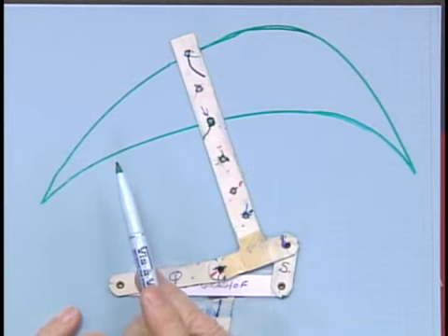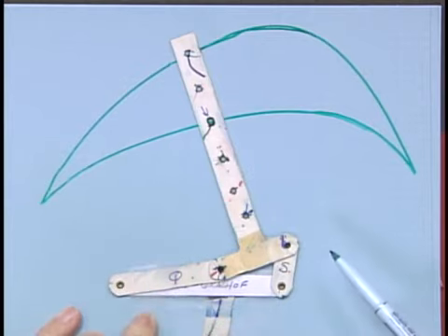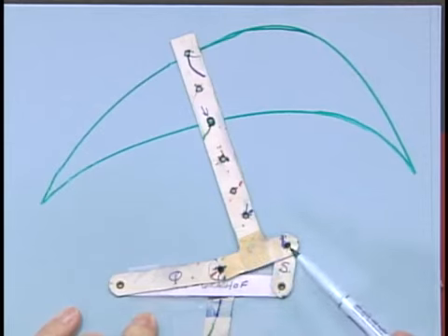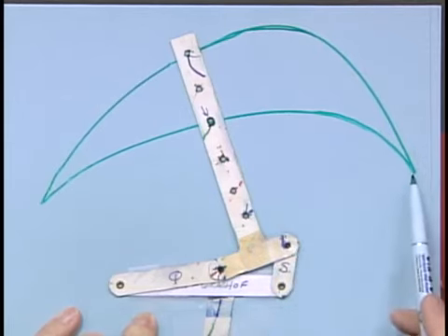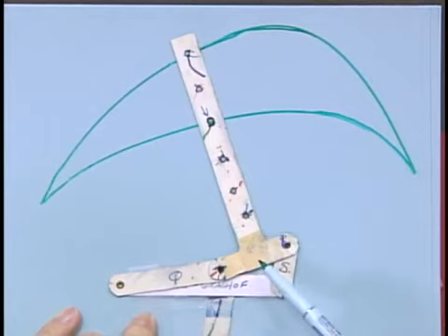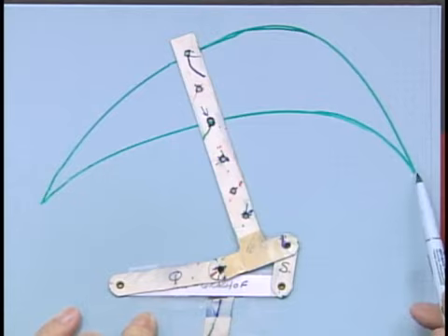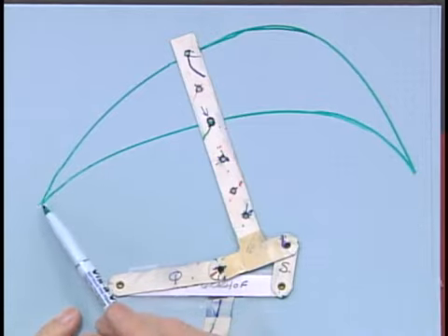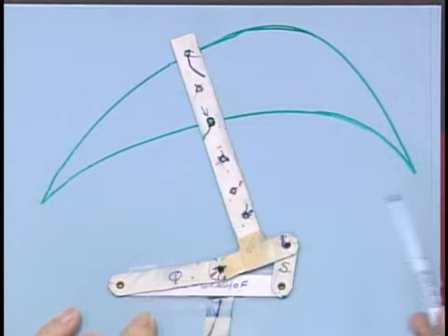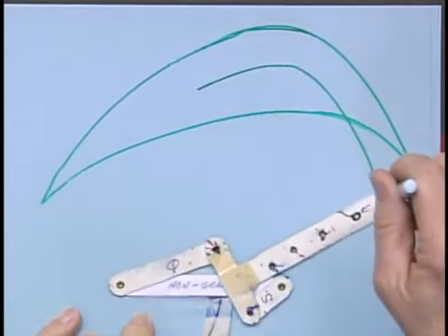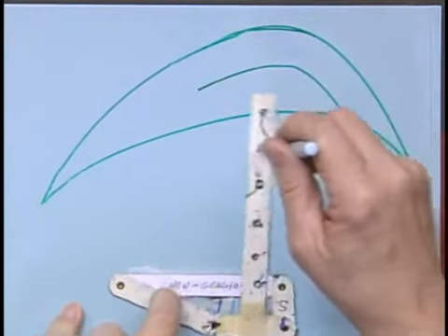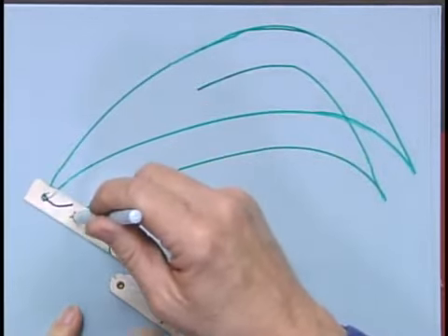Now here we have a more interesting looking curve. This is a non-Grashof linkage. No link makes a full revolution, but note number one, we have a closed curve nevertheless. So the coupler curves will be closed irrespective of the Grashof condition of the linkage. Number two, we seem to have two cusps, one here, one there, and some interestingly shaped curve in between. Let's try this point here and see what happens. Again, I'm helping it through the toggle points with my other hand.